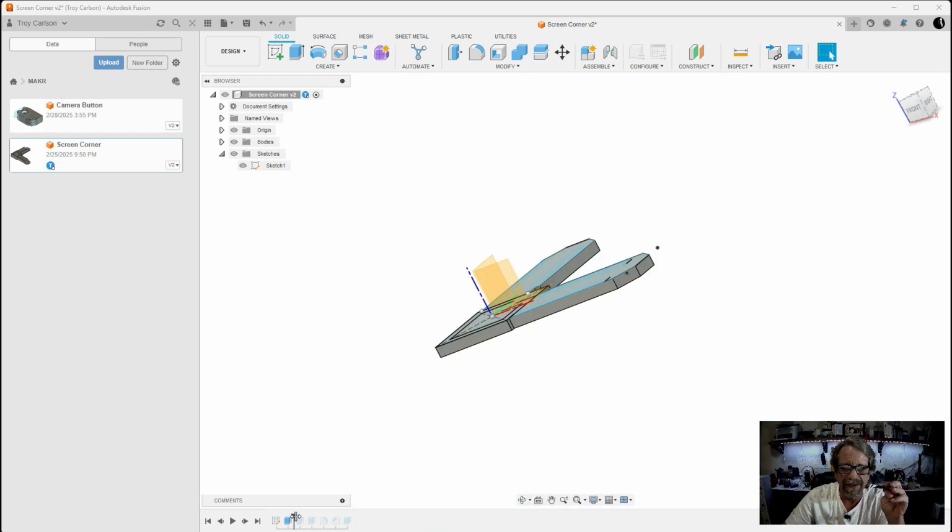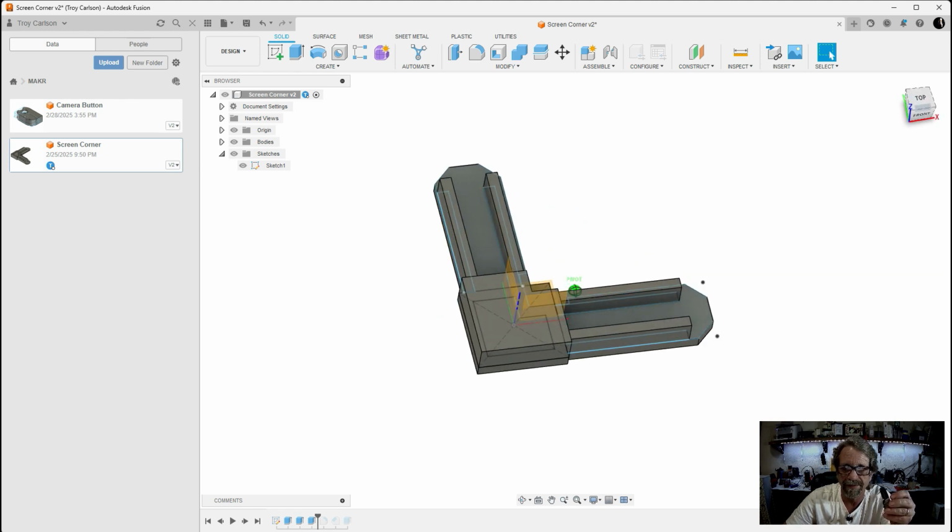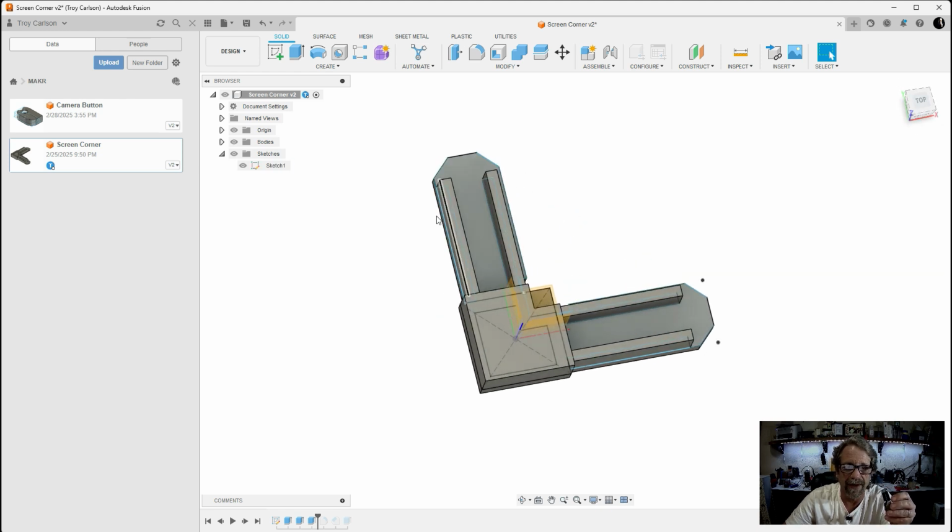Then from there, the next step, we pulled up the center rectangle. From there, we pulled up the two flanges for each side. And just so you know, I designed out one side, then picked all of it, and then used this line running across as my center line, and then just mirrored it from one side to the other. It's actually a pretty simple process.